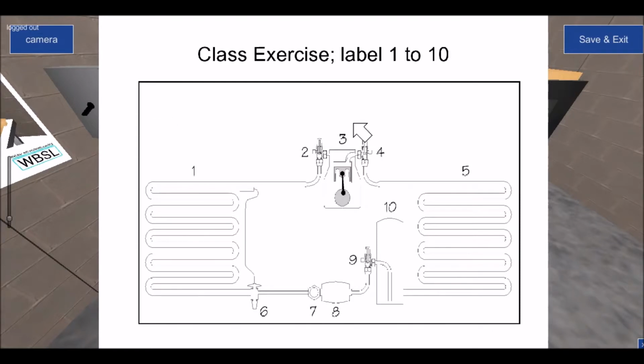And that would suffice as long as it shows that you understand the different conditions the refrigerant is at as it travels through from the condenser to the evaporator. So as it's pumped by the compressor to the condenser, from the condenser through the metering device into the evaporator, from the evaporator drawn back to the compressor again.